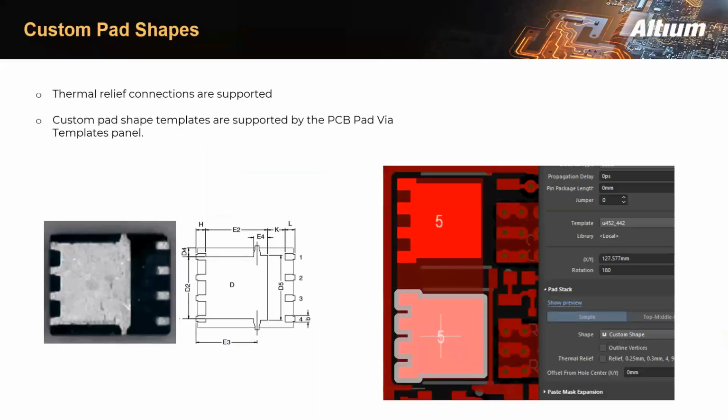We'll talk about custom pad shapes. In today's devices, we use a variety of components, including those with special requirements like pads with complex or, let's say, non-standard shapes. Now, Altium Designer is able to quickly adjust to these non-standard pad shapes. You are able to create these pad shapes by converting placed regions or a closed outline, or directly by using the shape dropdown from the properties panel. In the properties panel, you can also toggle on and off thermal relief and rounding of rectangular pads.